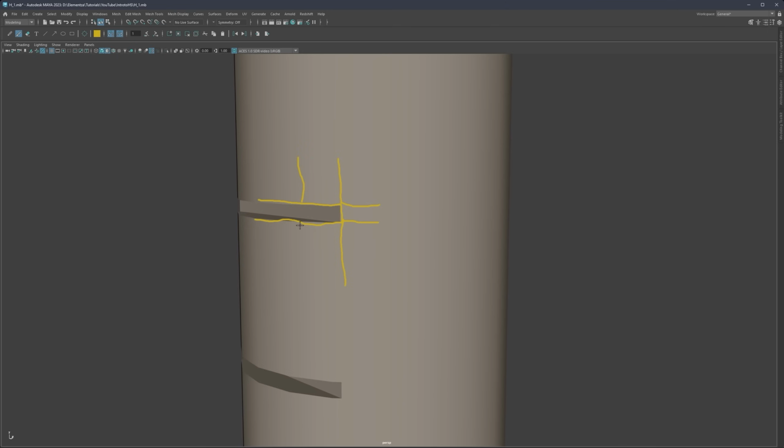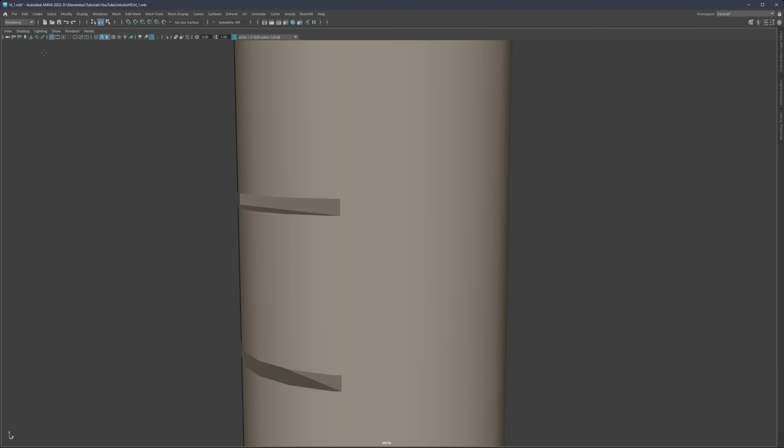And if we have widely spread edges, let's say like this, that means that this corner is not going to be sharp. And if we planned what we planned at the beginning, that we're going to need more topology to establish the top shape, that also simply means that the topology that we add later might be enough to actually hold this shape in place. So we can also delete this and delete that.